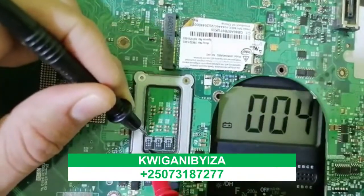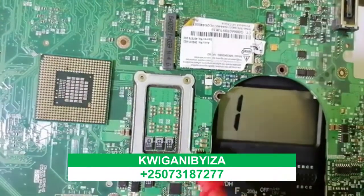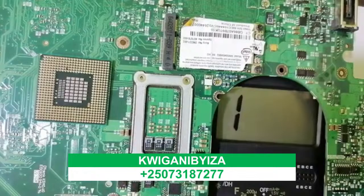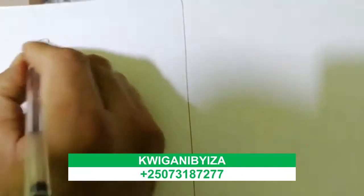If you check this one, as you can see, 0 in the multimeter. It means we have a clear short circuit in the CPU circuit, and I'm going to teach you how to find it and how to troubleshoot it step by step. So please remember, let's summarize what we have seen before. So ceramic capacitor, okay?